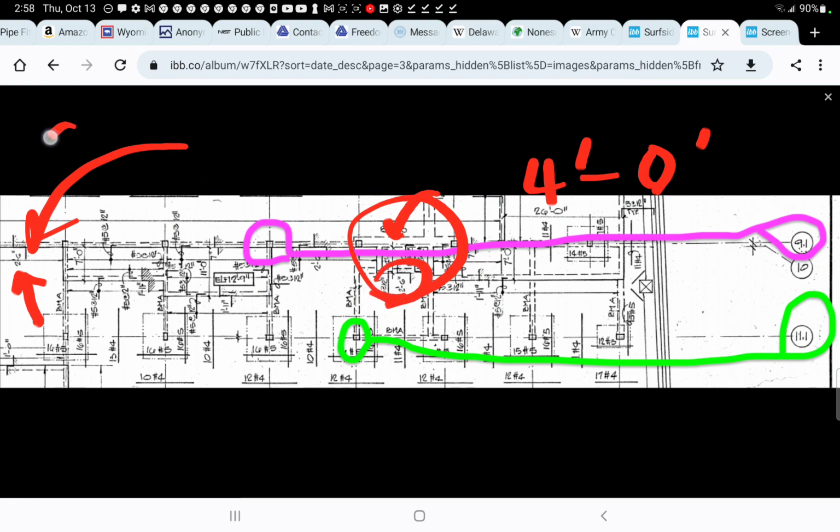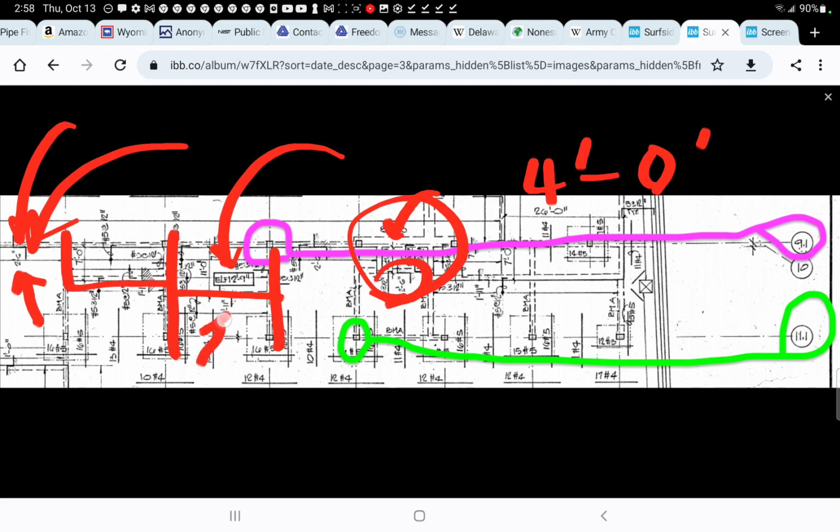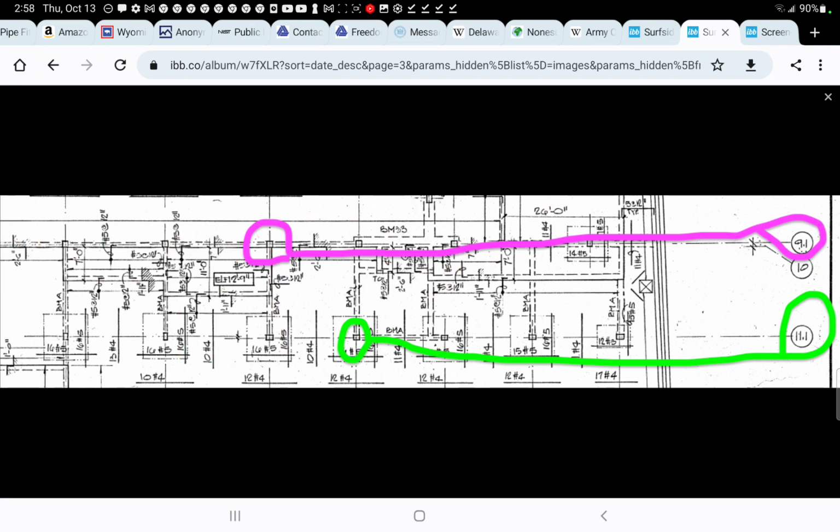So I believe that would probably drop down to 1.6 also. That is just adding the rigidity of it. We're out here where our deck, our BMAs are over here. 12'9", that's a different elevation now. Correction, I think it might be the same elevation. Just the thickness has changed. Here's 1'11", and so it would be 11 inches elevation change because the deck went up by 1 foot. Let's keep it going.